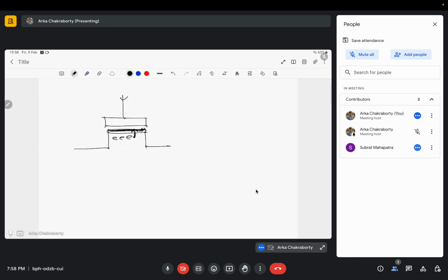accumulate here. If you remember from your semiconductor device physics classes in your second or third year, let me give you a brief idea. The threshold voltage of a MOSFET also depends on the charge present in this oxide region, Tox. So by inducing electrons here, we can simply shift the VT. We can change the VT.